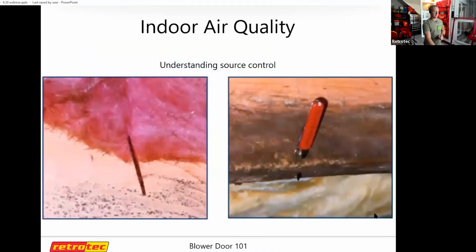Same here. If you have this stuff growing, this is in a crawl space. So I'm a big fan of encapsulated crawl spaces for this reason here. So this is in a vented crawl space, mold growth, rot occurring. And then on the floor above that, you're really breathing this stuff in. This air down here eventually makes its way up. So we don't want that to happen. So we want to be able to control that climate a lot better by keeping that outdoor air out, keeping that humidity out, and allow us to control that indoor climate so this stuff doesn't happen.